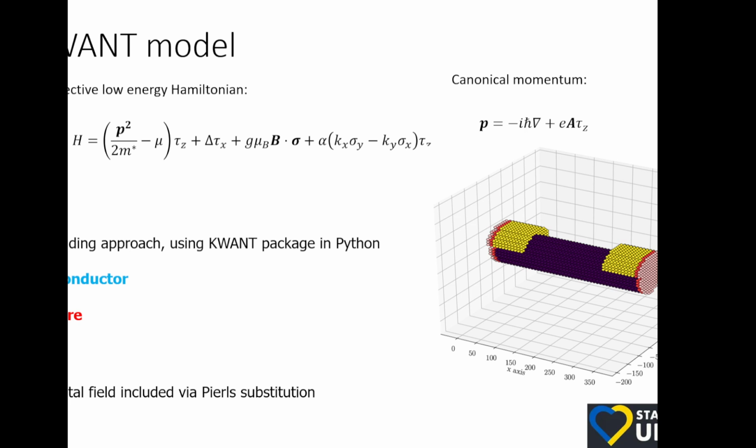here in quantum transport calculations, you can see how many there are across maybe 10 sites, right? And the nanowire has about 1,000 atoms across, right? So each site is a representation of transport in this device, not corresponding to one atom, right? And so then the on-site energy and the hopping term do not correspond to the orbital in an indium or antimony atom, or the band curvature, the velocity. They don't correspond to that, the coupling of the two orbitals. There are some effective parameters, but it looks like that.